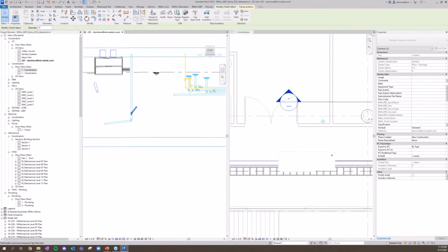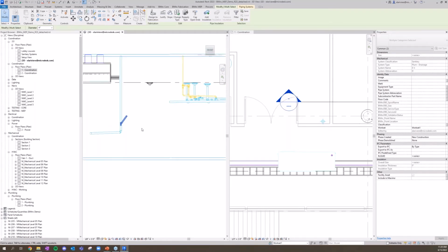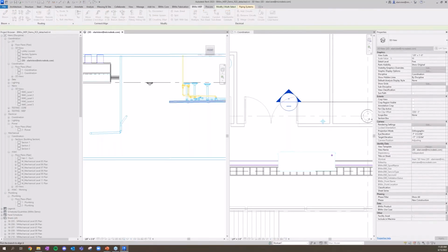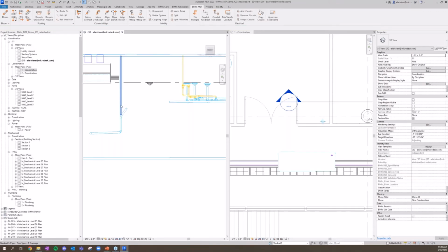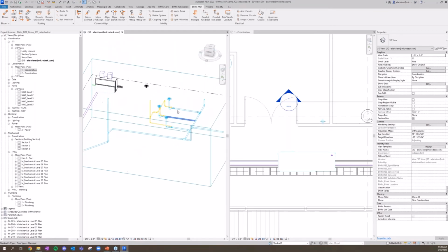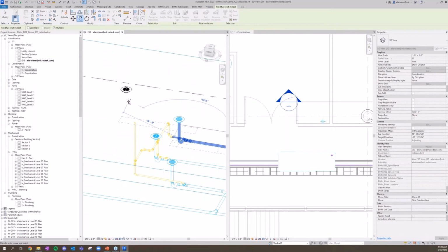Looking over on the side there, I now need to line these things up. Well, we've seen me do an align branch with individual elements. Turns out we can do a pre-select as well. Doing a pre-select will force all of these elements to only move in one direction. What's that mean? That means I can absolutely use align branch and see this only shift in the vertical to allow me to use trim extend to corner for that final connection. Very, very quick process. I can then maybe route up the final bit over here.